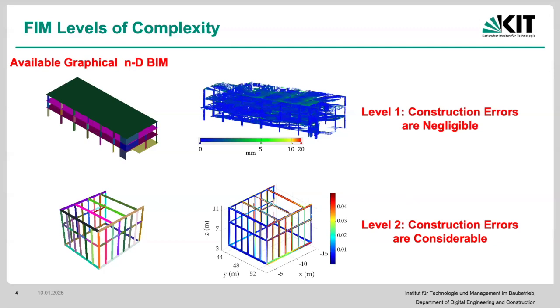With respect to this, we have to have a better solution to be able to identify these errors and to observe how far these errors are from the actual tolerances. If, again, this is very small, it's not going to be problematic. But that by itself is important for us to define. What is this small? Is it 5 centimeters? Is it 4 centimeters? Is it 10 centimeters? What is it? For that, whatever method we devise in order to process this needs to be immune and robust to larger errors, right? That by itself means that the method needs to be a bit more complex than just seeing the distance between every point and the surface and then making a judgment based on that, right?